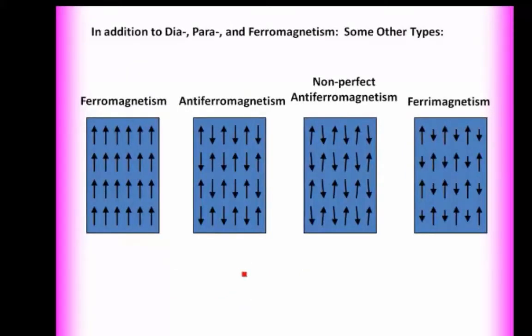Just to finish then, I wanted to just very briefly mention two other types of magnetic materials. This is the case of the aligned ferromagnet. There's another type of ordered structure where the domains form this pattern here so that they're in opposite direction as you go across the material. So initially, when these were disordered, you put it in the field and you have this ordering that's in the opposite direction. And so that's called anti-ferromagnetism. If you heat this material up, then you start to disorient this material, but it still tries to stay with this type of order here.